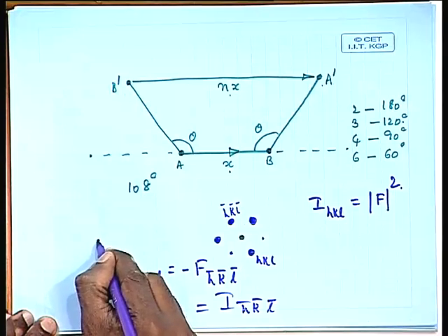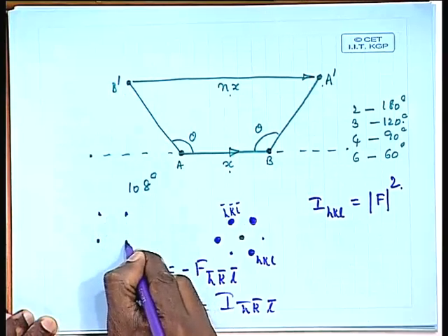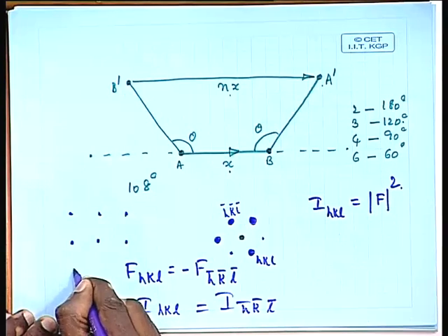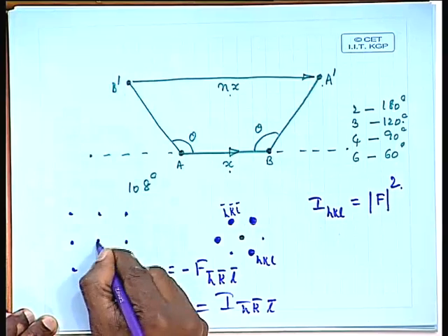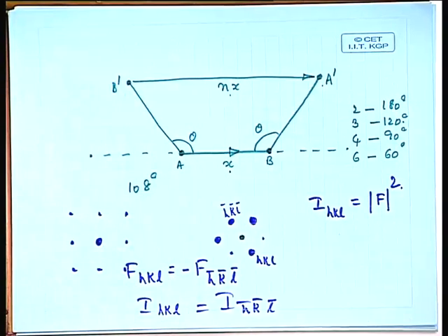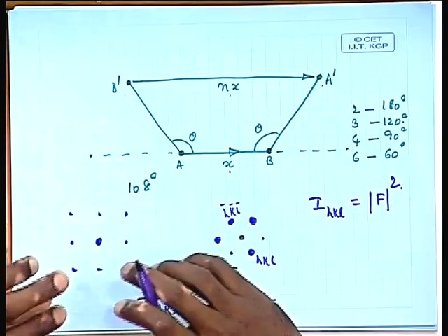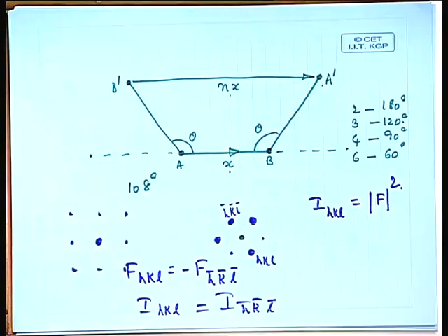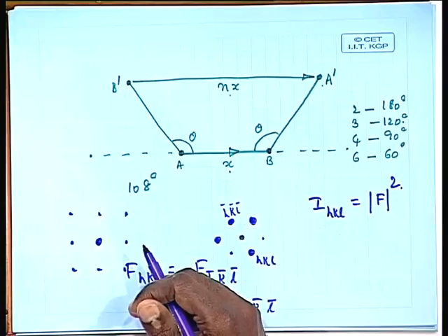When I tilt my sample, I can change its orientation from the 1-1-1 orientation to some other orientation. If I change this orientation and get a 4-fold kind of symmetry, a symmetry which looks like this, with a central transmitted spot, that is because after a certain rotation the diffraction pattern changes, as some other plane comes perpendicular to the electron beam.